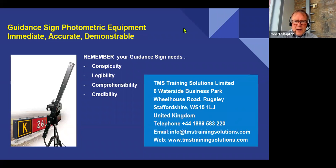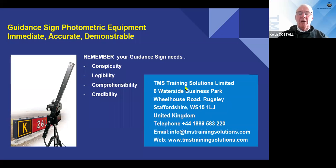Cathy Velu would like to know how far guidance signs should be placed away from the runway center line as the runway width varies. Where can he find that information? Can you just point it out? No, it's not about where the guidance sign is according to the center line of the runway. It's from the table I showed in our presentation, and it's from the runway edge. So the dimension is from the runway edge, not from the runway center line.